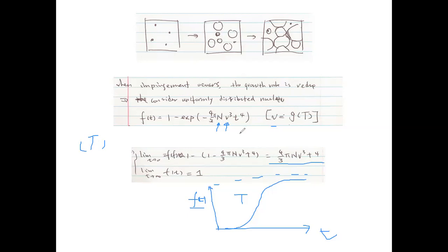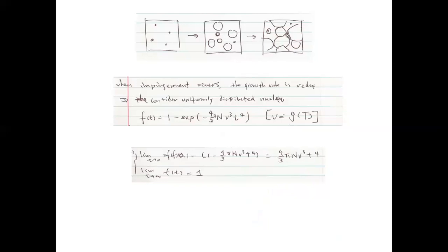Now, if we have a different nucleation kinetics, where do you think we're going to modify or change the equation? Without spending too much time on this, we see that when we change the kinetics of the nucleation, this scaling changes, right? For the saturation case, we have t raised to the third power, but for this cellular transformation, we have t raised to the fourth power. So this implies that if I change, in general, the nucleation dynamics, then I can change this power in time.